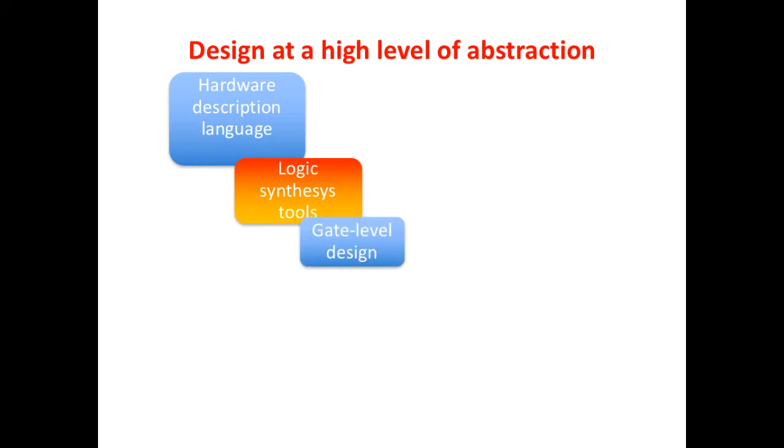Then once you have the hardware description language, you can use some specific logic synthesis tools in order to translate this description in terms of a high level language into a gate level design. So one typically describes the operation of the integrated circuits at a high level of abstraction.